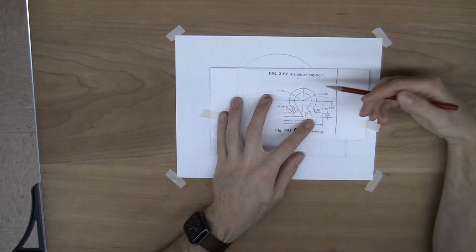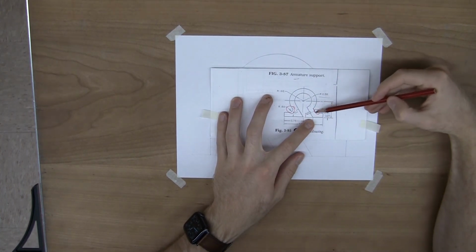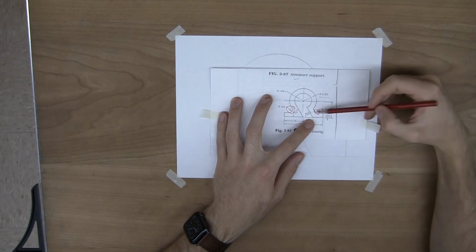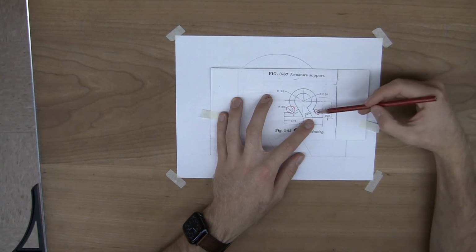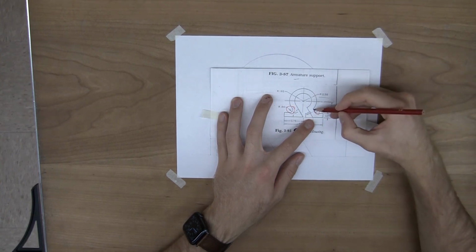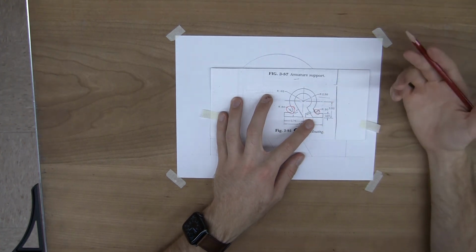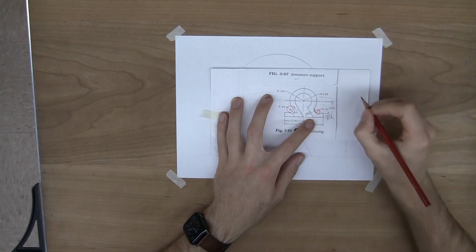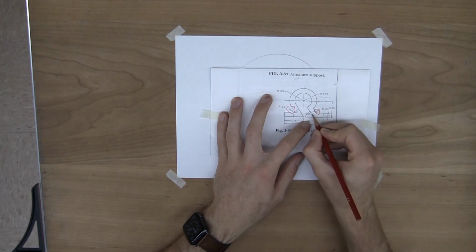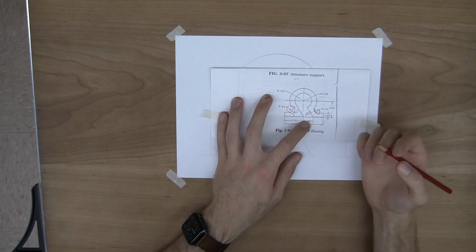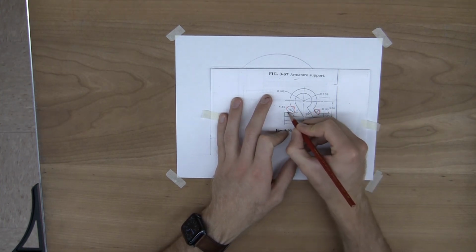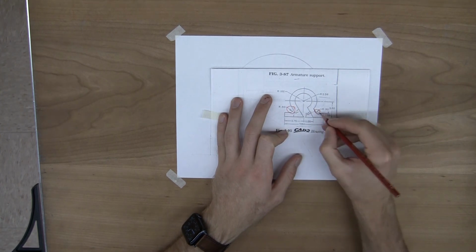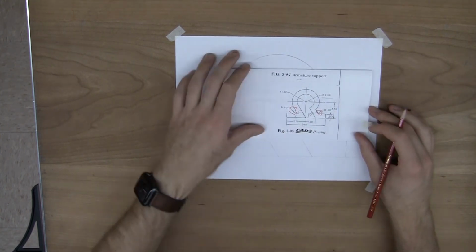Right here, this part, the two red circles, the two parts that are circled in red, we will get to in a minute. But first, there's this line. This line is parallel to this line and this line, so we know it's at 60 degrees. And it's a certain distance away. Thing is, we don't know the distance. Well, what we're going to do is infer it off of other measurements. All the other sections of the base are 1 inch, so that will also be 1 inch.